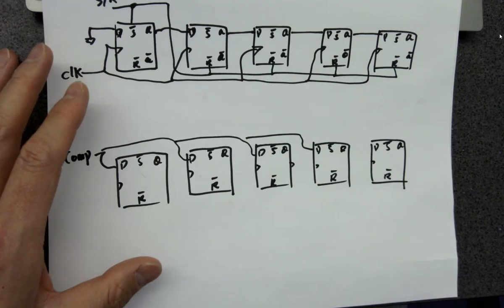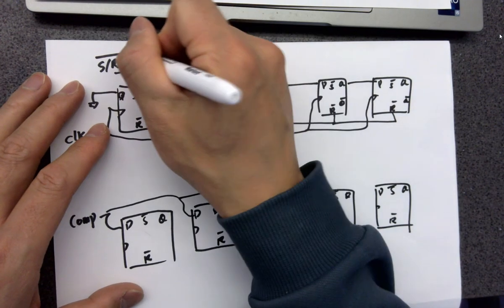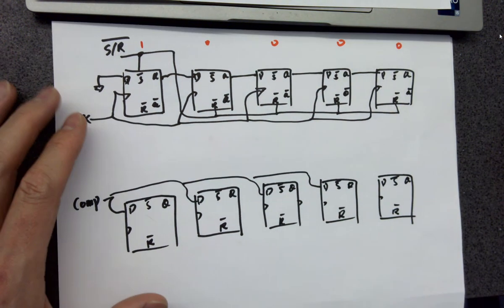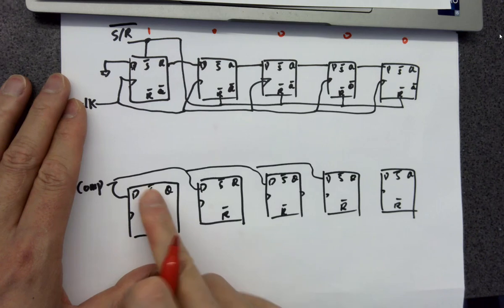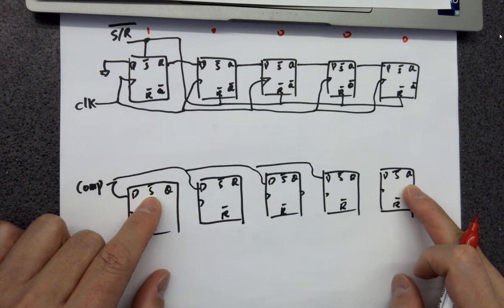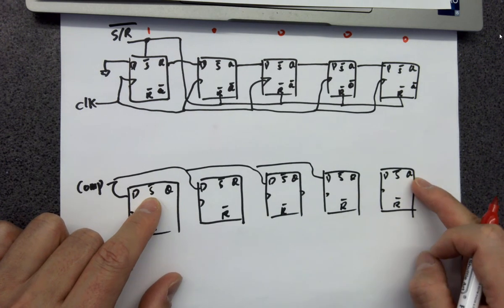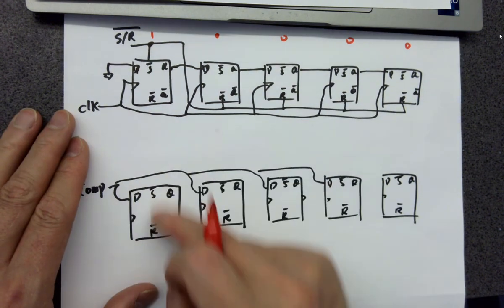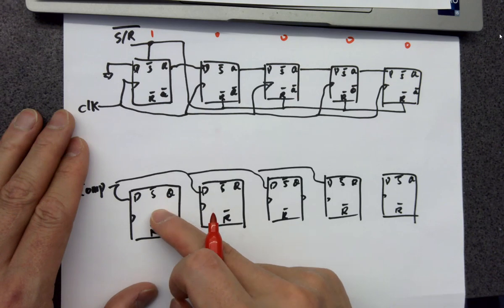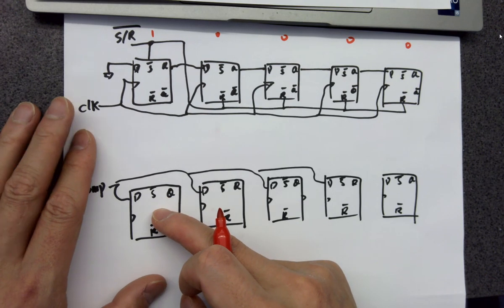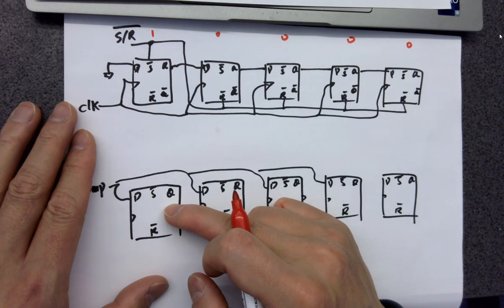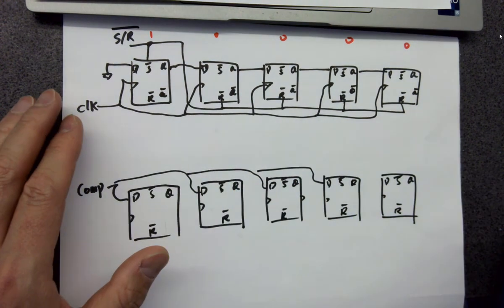So let's think about one key point over here. Whenever I'm setting, I'm getting 1 and zeros. And these guys also need to be set and reset as well. They need to be set as well because it's trying to pass that 1 here, so it's able to set it. But the thing is, this is also active low. So you cannot use the 1 to set it. What's the solution for that?